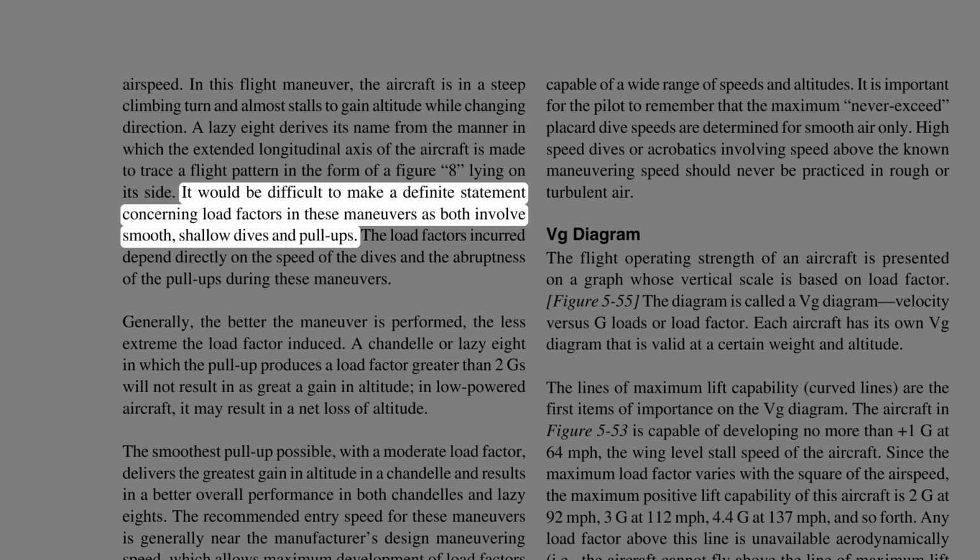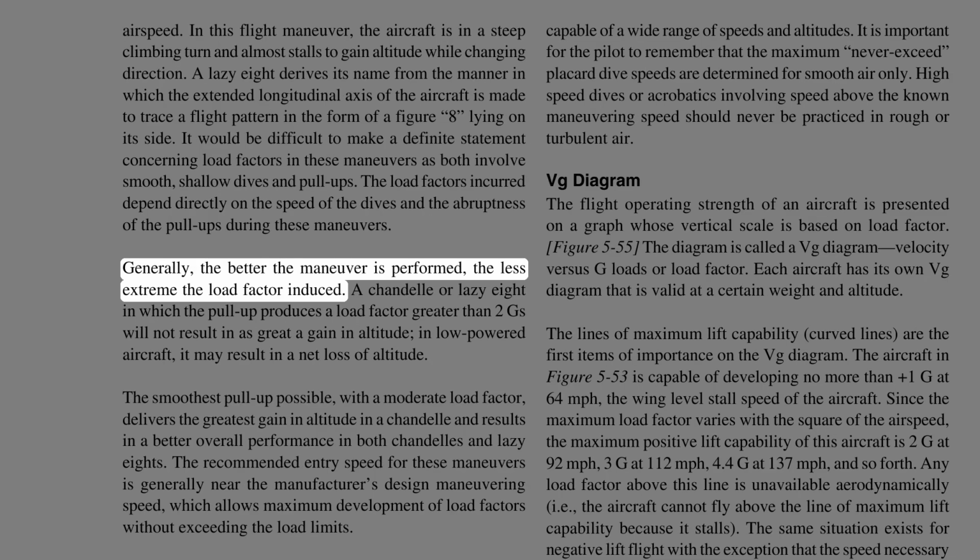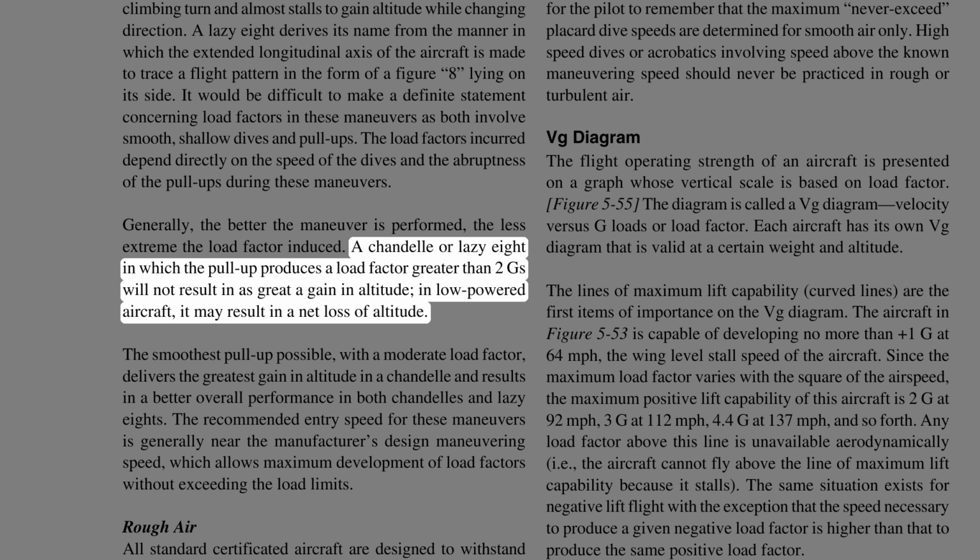It would be difficult to make a definite statement concerning load factors in these maneuvers as both involve smooth, shallow dives and pull-ups. The load factors incurred depend directly on the speed of the dives and the abruptness of the pull-ups during these maneuvers. Generally, the better the maneuver is performed, the less extreme the load factor induced. A chandelle or lazy eight in which the pull-up produces a load factor greater than 2 Gs will not result in as great a gain in altitude. In low-powered aircraft, it may result in a net loss of altitude.